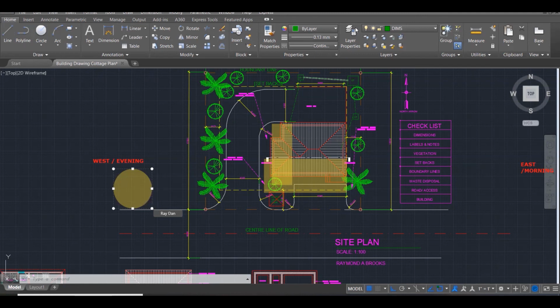But if you have a bedroom on the west side or the south side, you are going to be in a lot of trouble. It's going to be quite uncomfortable in the evening time, especially if you don't have an AC unit to cool down the place. So by knowing where north is, you can tell which bedrooms are going to be cool from which are going to be warm, or generally the warm and the cool parts of the house, not necessarily a bedroom. But that's the advantage. You can also tell where the wind is blowing. Different things you can determine once you know where north is on the site.